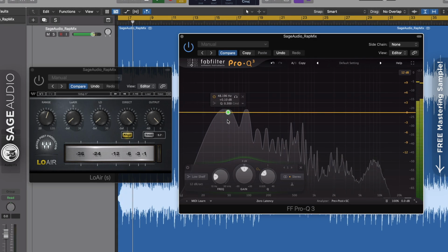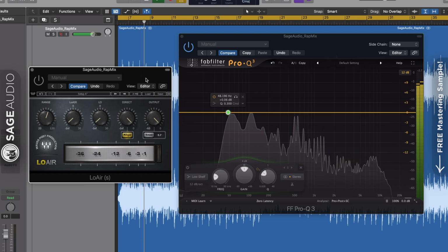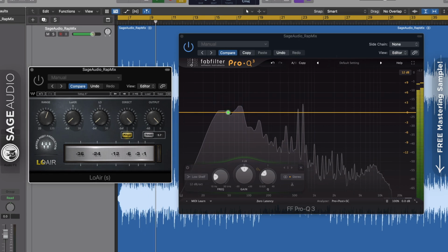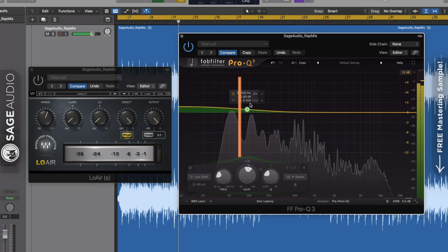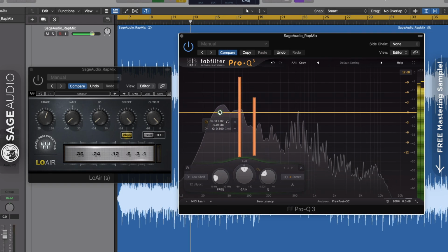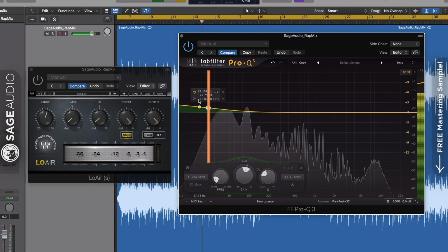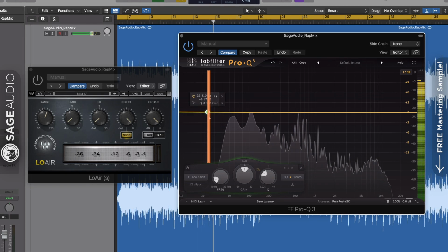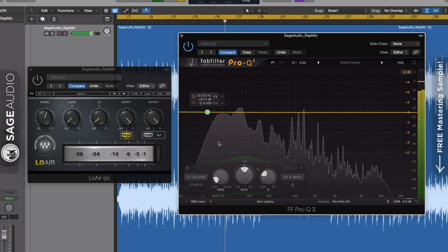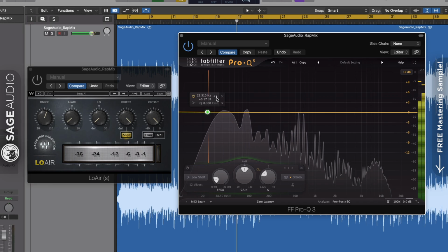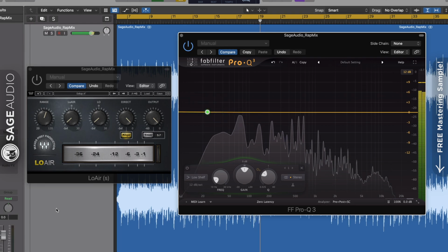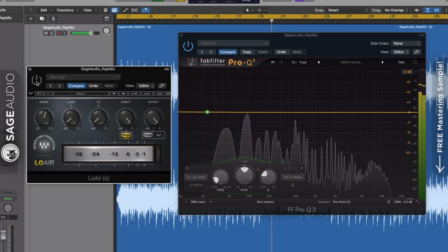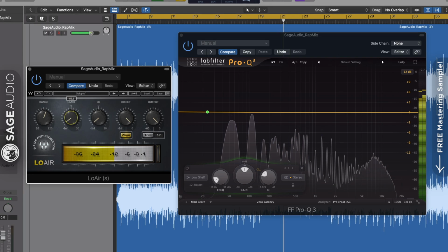Now, if you find yourself in this situation, you can use a sub-frequency generator, whereas typical distortion and saturation plugins amplify and create harmonics above the fundamental. A sub-frequency generator will create a frequency below the fundamental. It does this by measuring the signal, finding the fundamental frequency, and then generating a pitch-shifted version of it further down the frequency spectrum.